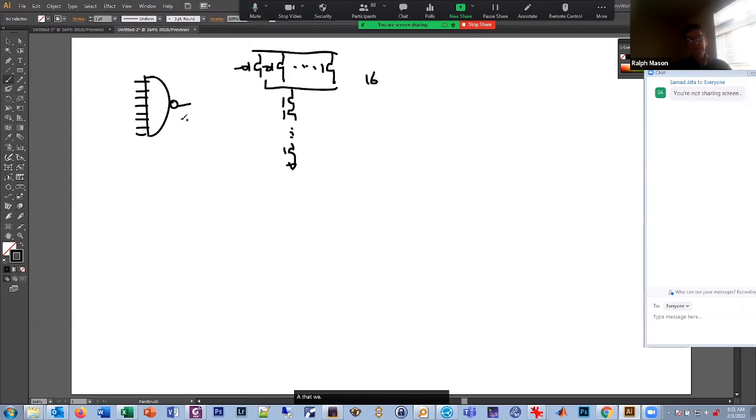We call that a static CMOS because once you apply some inputs and you have some capacitance here, you either have the P channels driving the capacitance or the N channel. So the output is 0 or 1, and it's held there. And as long as you have power applied to this gate, it could hold that signal on the output forever, basically, as long as there's power. Now I'm going to make a dynamic version of this.